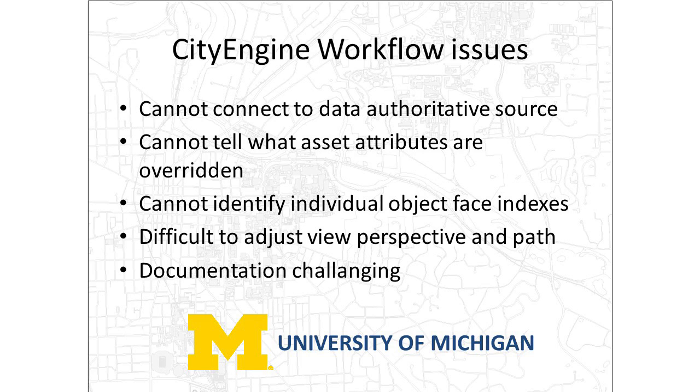Another big issue, yes? You skipped over the SDE thing, and I was hoping you would talk about that. Yes, all right. It cannot read SDE data directly. The claim at the 3D conference was that in 2.16 they're going to address that issue and fix it. So right now what we end up having to do is export a file geodatabase in 2.14.1 or below, and then we can read it in.